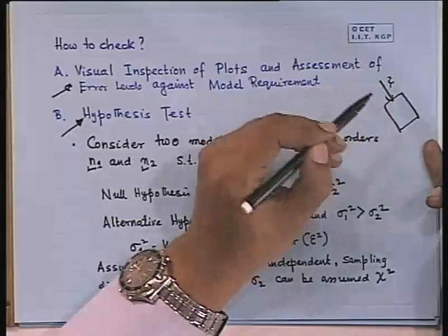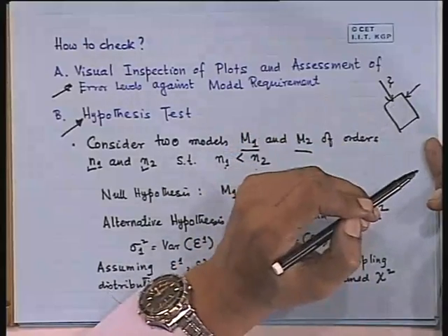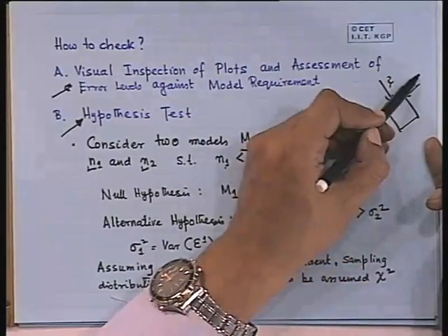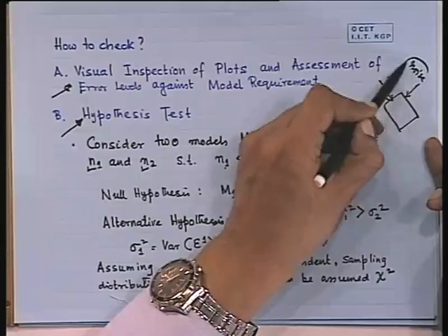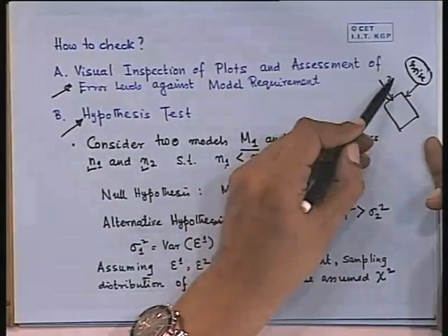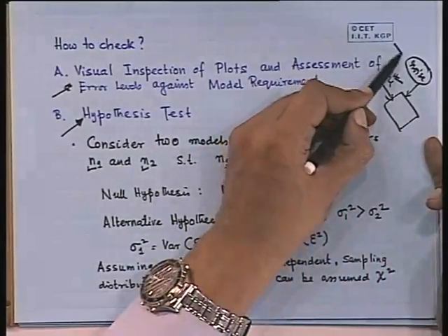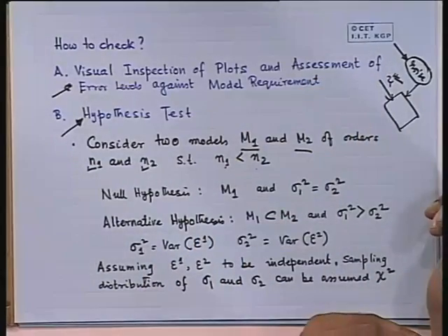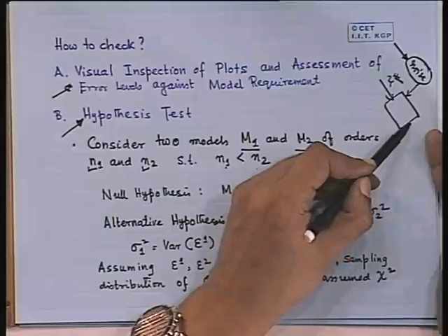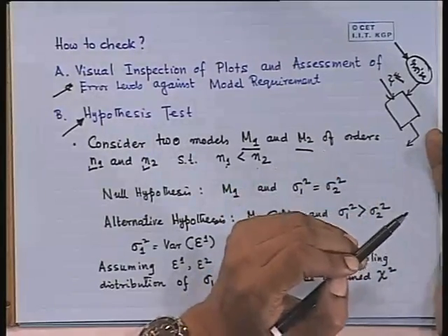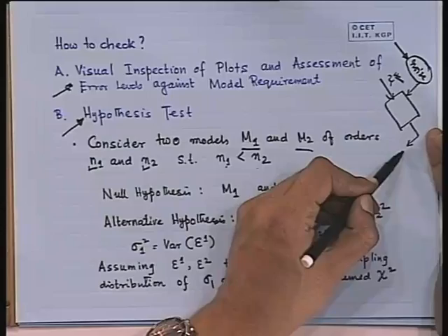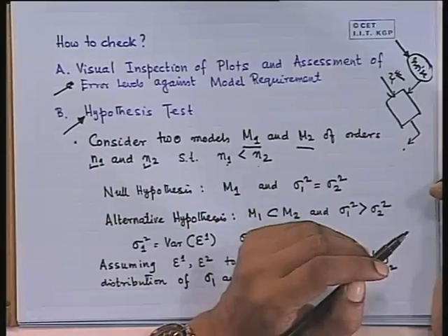See how our output is being generated: there is an input and there is some random element, which is my noise. If I keep U and do 10,000 different experiments, I will get 10,000 different noise elements, because that is a random variable. If I do an estimation with that, I will get 10,000 different prediction errors. Physical sequences will be different, so they are also random processes.